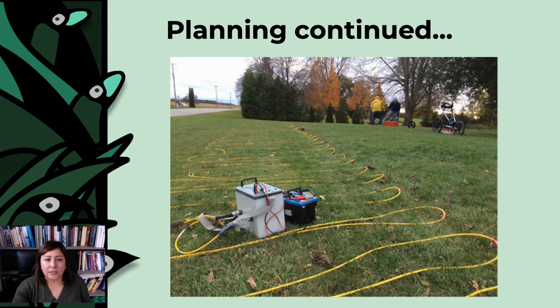In contrast, ERT systems take longer and are more stationary. They require the operator to place a line or grid of metal electrodes and allow the computer to calculate the ground resistance over a period of time. Once the calculations are done, the electrodes are removed from the ground and planted at the next survey location, which can be done in a grid with consistent intervals.